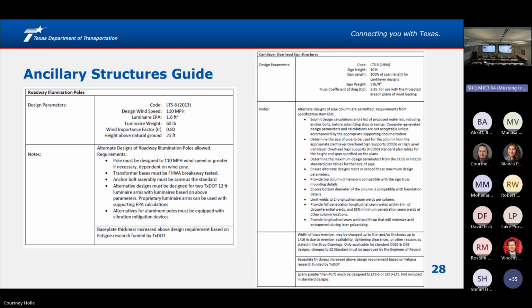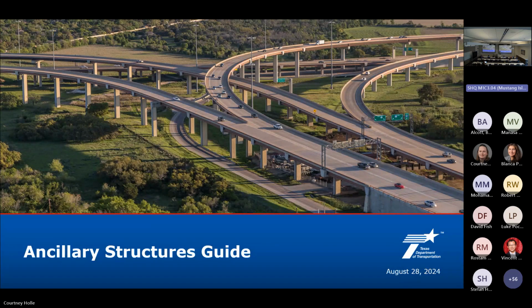If you want to design it, an odd situation might be, okay, you're doing a toll structure, it's got equipment. Well, you've deviated from what you've got, and in tolling, there's deflection, displacement, rotation criteria, so maybe you need to beef up the web members. Anything that's outside the limits of the standard. Oh, the question was, what makes it a special zone?